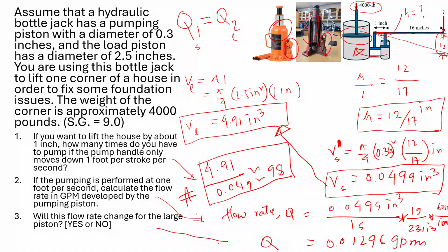The next question is asking, does the fluid flow change? No, because of the continuity law. Whatever flow rate you are developing here, the fluid will go at the exact same rate in this piston. So Q small is the same as Q large.